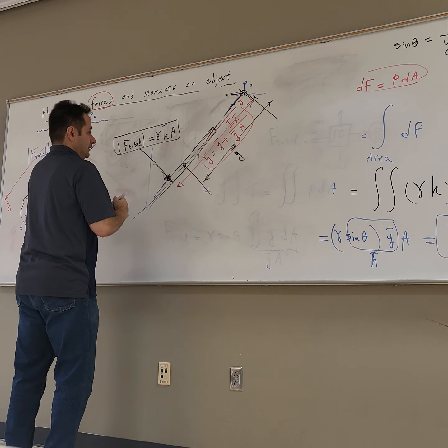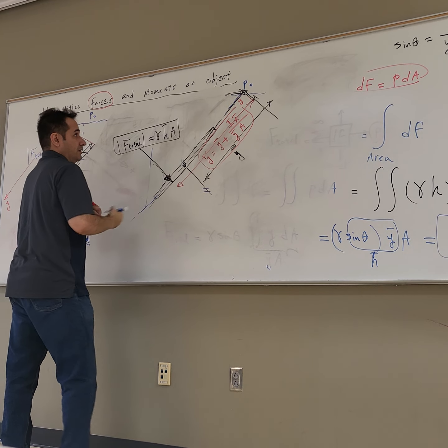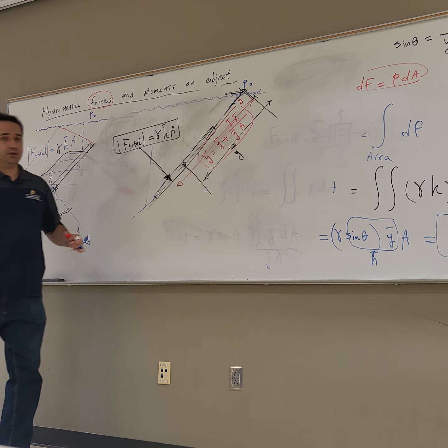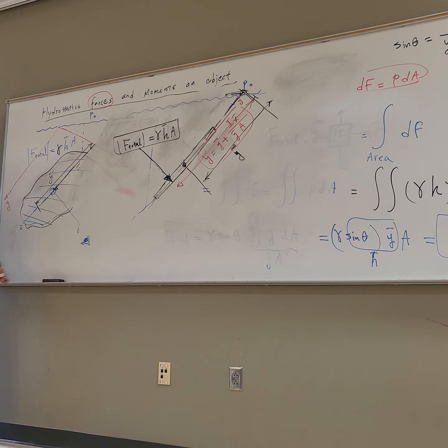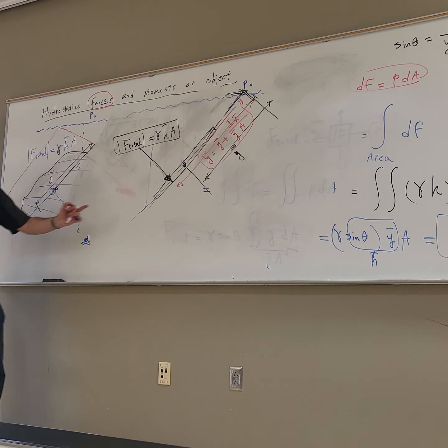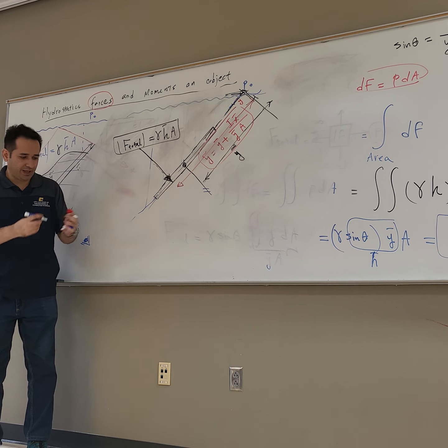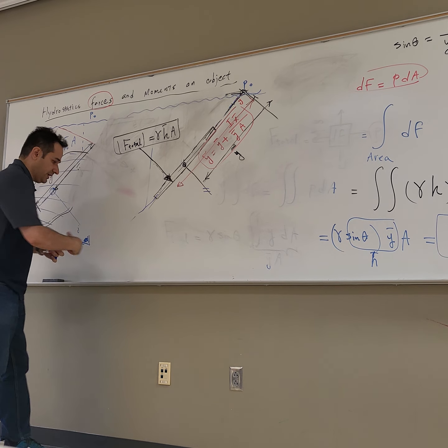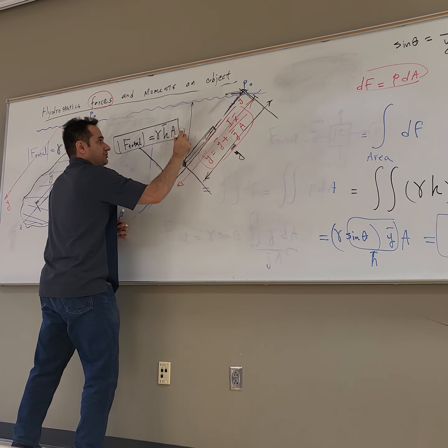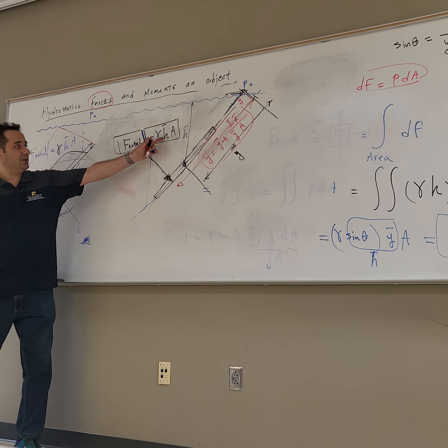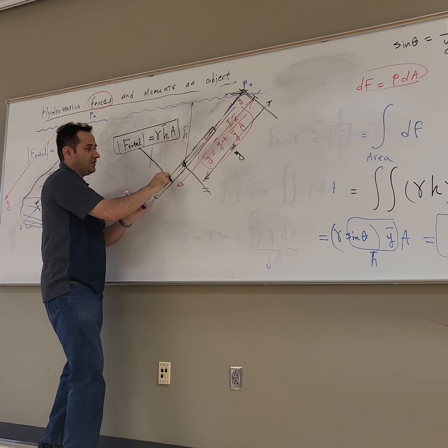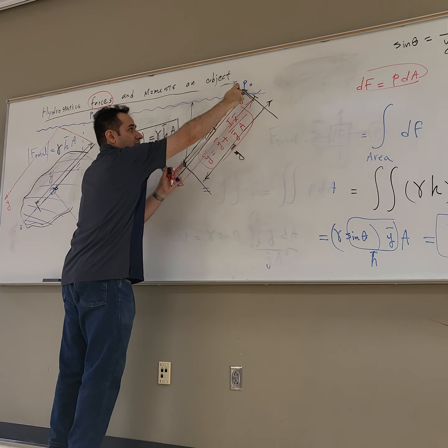And this is the surface of water. That's the surface of water. So this is P0. Let's look at it one more time. That's the plate that you look at from the side, right? And let's say this is the centroid. So that is the depth of your centroid. From here to the surface is your h bar. If you put it in the formula, you get F total. Now the location that it is acting, from here to here is y bar.